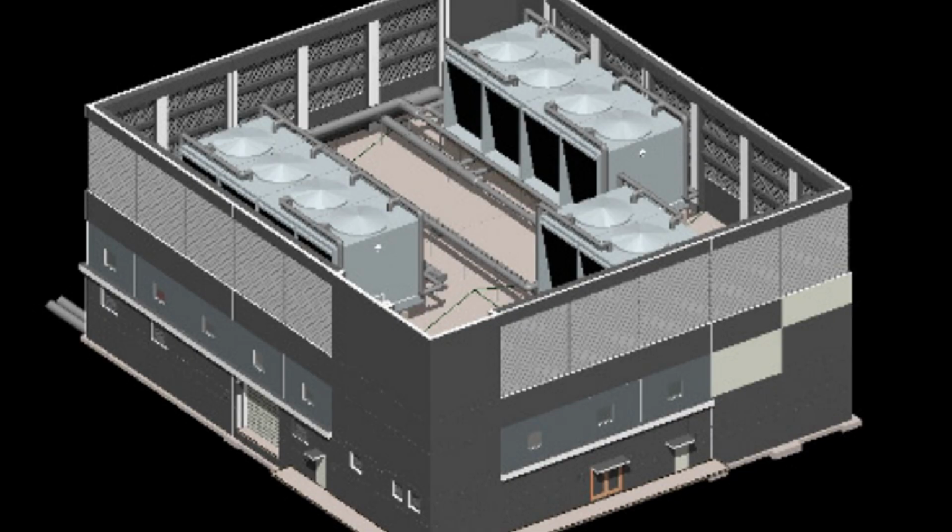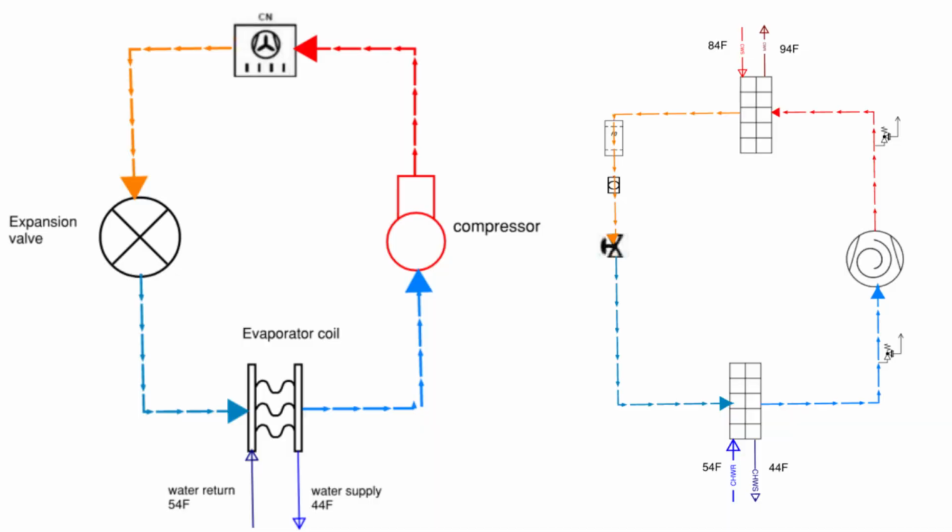To make this process work efficiently, 5 functional parts must work together: the chillers that generate cold water, the loads that absorb heat, the distribution system of pumps and piping, the heat rejection system, usually cooling towers or condensers, and the controls that synchronize the entire plant as one integrated system. Chillers are the heart of any plant.